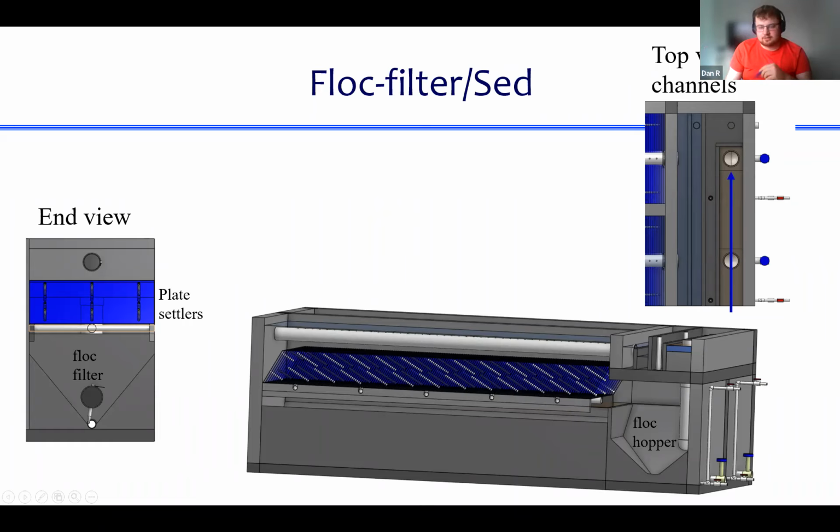What are those tiny white pipes at the bottom near the end, closest to us? This one? Or yeah, in either view. Okay. It's the right place though. This one is a tiny little 1-inch diameter diffuser. It takes the water from the inlet manifold and forces it to go straight down into a little jet reverser right here. And so the water goes straight down, it exits right here, and then turns around and goes up. And we'll talk more about why that happens. It ends up being a key part of our design.